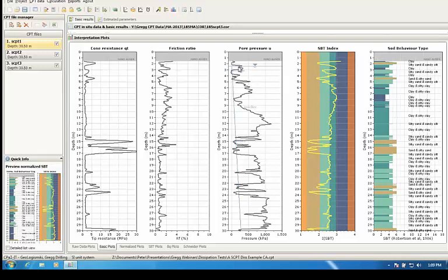If I blow that up a little bit, you'll see it a little bit better. So you can see it did start slightly negative and rose up. And this one was at 3.2 meters. If we go back to the profile, at 3.2 meters here, you can see there was a little bit of a clay layer and then into sand. And so right at 3.2, you're just pushing into the sand.